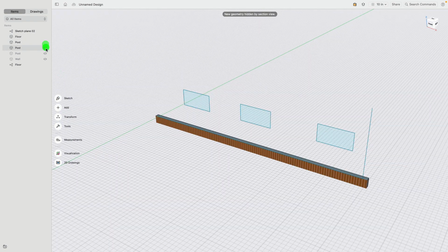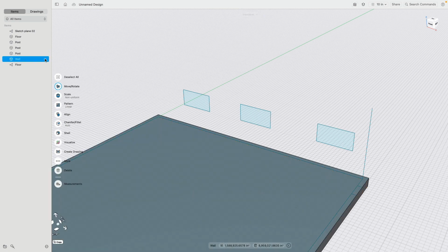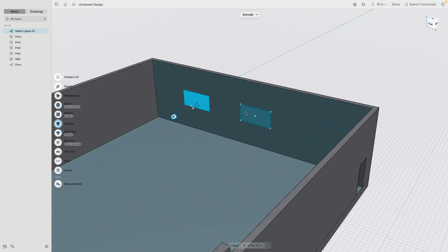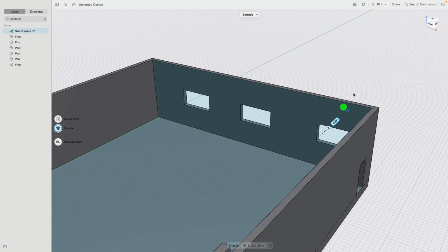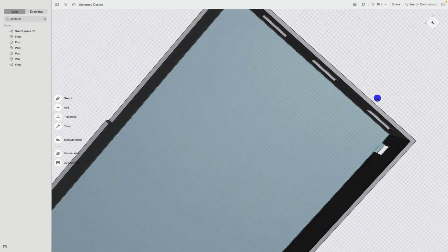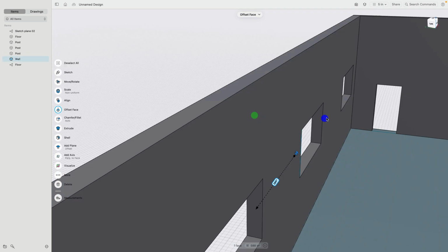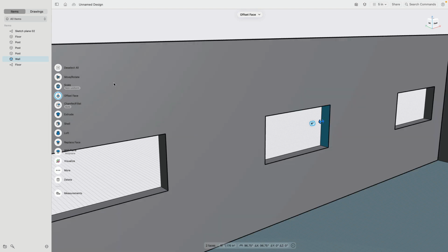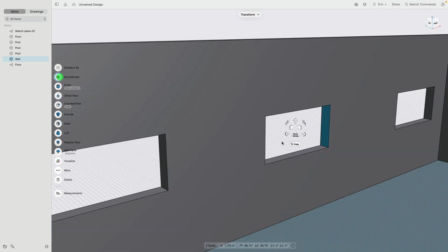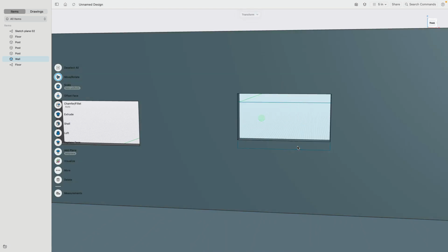Exit the sketch, show everything. We have to turn off section view, and then we can shift click the profiles, click and drag, and cut through. Yeah, that's how easy actually it is to create this. Just as an explanation, we can always later select these individual faces, for example, shift and left and right, and then even move things around now if we want to.